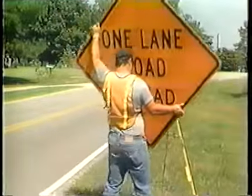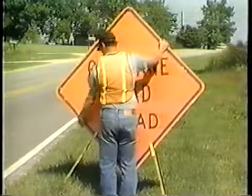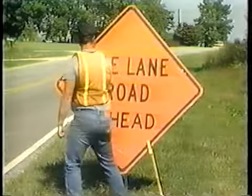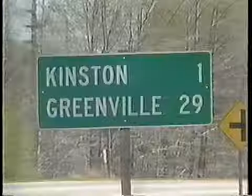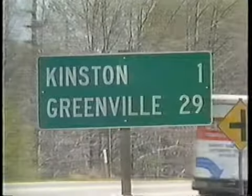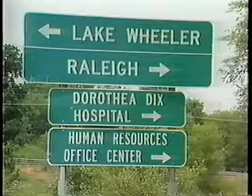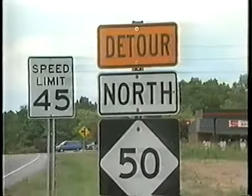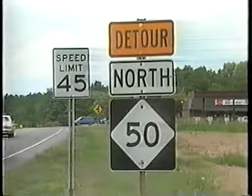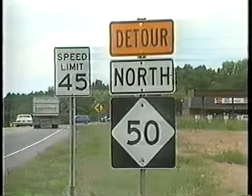Warning signs should be placed well ahead of the site to give the motorist enough time to understand and then respond to the information. Guide signs show destinations, directions, services, points of interest, and other geographical or cultural information. Informational signs are required at work zones for standard route markings when temporary route changes are necessary.